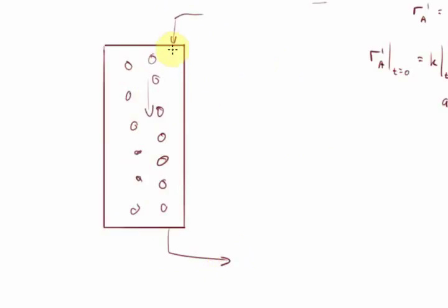And of course, as they are falling, they are picking up whatever it is that's causing them to deactivate, or they are just deactivating. We don't have to specify the nature. We know we are losing activity quickly. So we are losing activity as it's falling. That means as we look down this tube, we are seeing a loss of activity. So let's call Z the axial distance down this tube. And we can say then that activity is a function of Z, right?